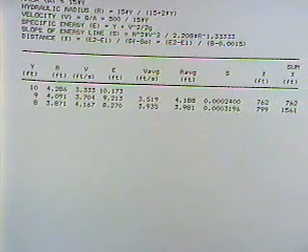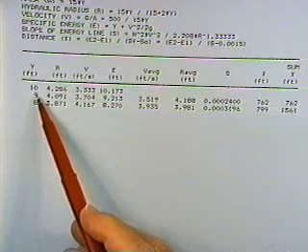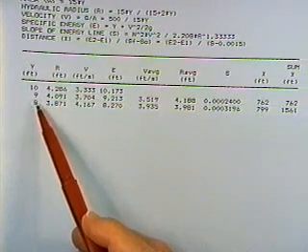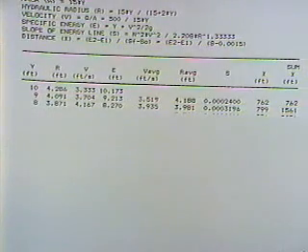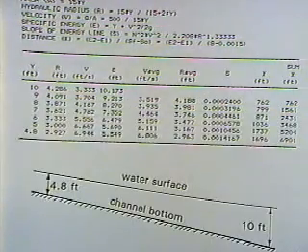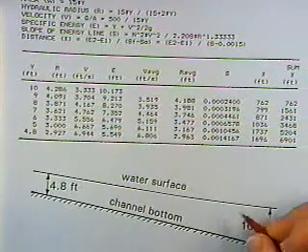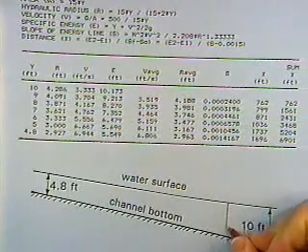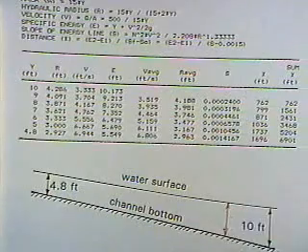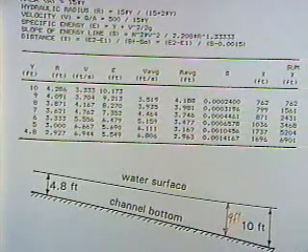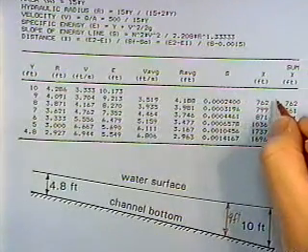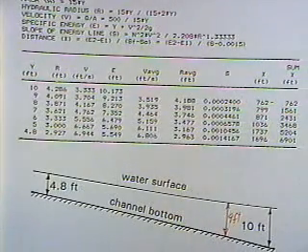So we go down another line and look at one section where the depth is 9 feet, at another section the depth is 8 feet, and we do the same computations all over again. And we just keep going. And so what I've done is there's 10 feet, someplace the depth is 9 feet, and I used the energy equation and computed a value of 762.